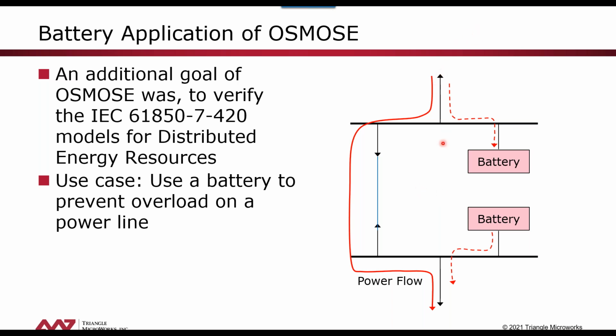So what we see here, we have our two substations that Matt has shown before that we simulate. We have the power line between them, and we assume now in a first step a power flow going from the one substation to the other substation. So this will be the collective sum of all the other feeders except the ones to this power line, and the same on the other substation. That would be a summary load out of that substation, and the energy has to flow over this power line.